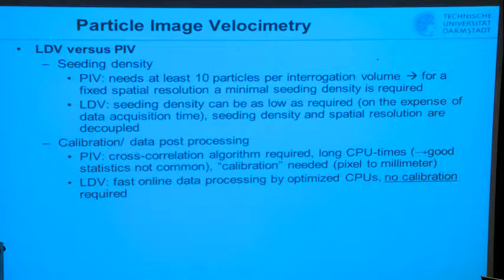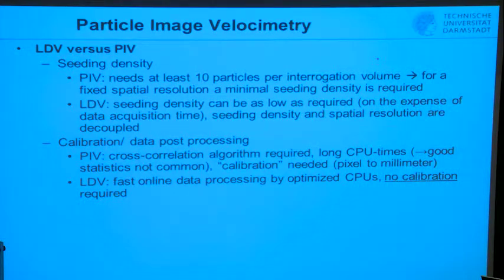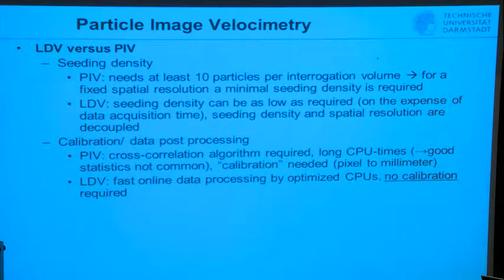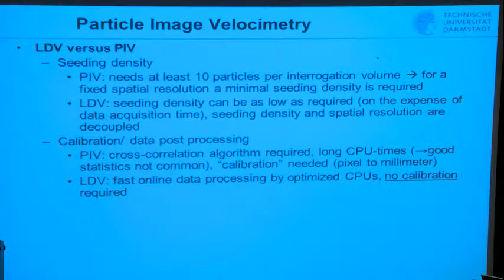Okay, another point is you have to do the calibration. We just discussed that with the calibration target. That brings you from the pixel to the millimeter scale, or from millimeter to pixel scale, and is really dependent on the way you do that. Do it thoroughly and it's okay, but do it as well with this self-calibration I mentioned briefly. If this is not done properly, you're inaccurate. Your results will be false.